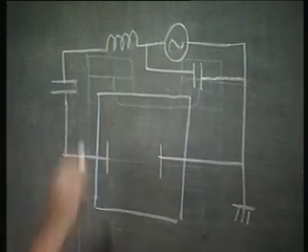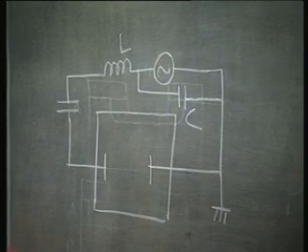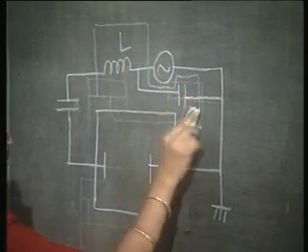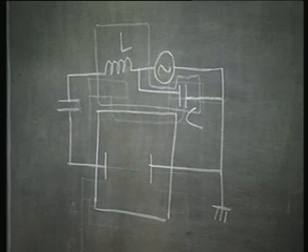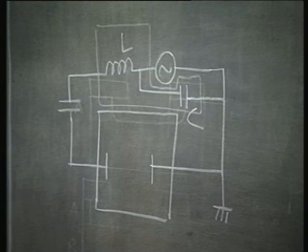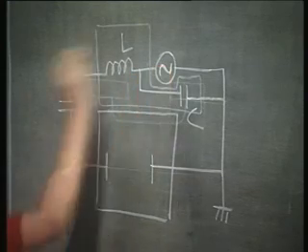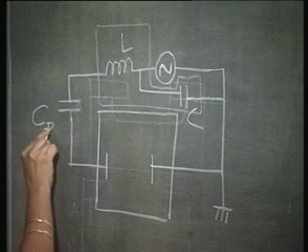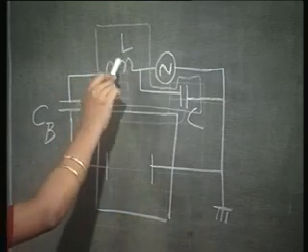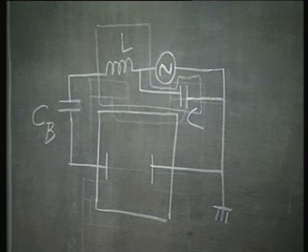This is actually your matching network, this LC. This is your matching network in order to minimize the reflected loss. Essentially what you have is this RF source, via a blocking capacitor, given to one electrode, and the other electrode is permanently grounded. This LC network is simply the matching network because you want to minimize the reflection loss.